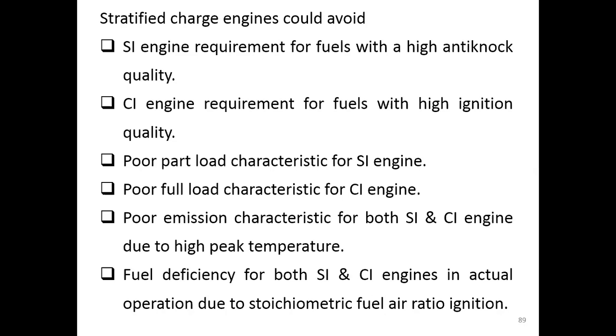But since our mixture is not homogeneous, our fuel need not be a high octane number fuel, as the SI engine would like to have. The CI engine requires fuel with high ignition quality, fuel that can ignite itself. But the stratified charge engine doesn't require the fuel to have a high ignition quality because it has the spark plug.